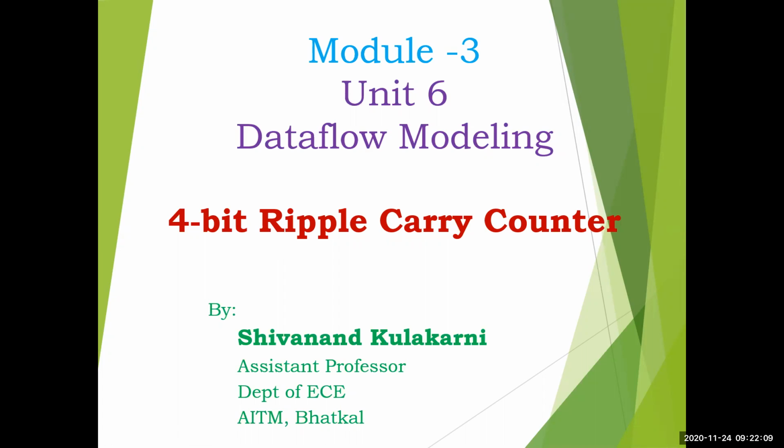Just the logic diagram I will show you. From the logic diagram, how to write the boolean expression, you are familiar with that, right? In digital electronics, in basic electronics as well as DSD, you have written that. If an expression is given, you write the logic diagram. Similarly, if a logic diagram is given, you know how to write the boolean expression. So using that boolean expression, we will write the lower level module of the D flip-flop. Remaining all is the same, so now the concept is more clear to you.